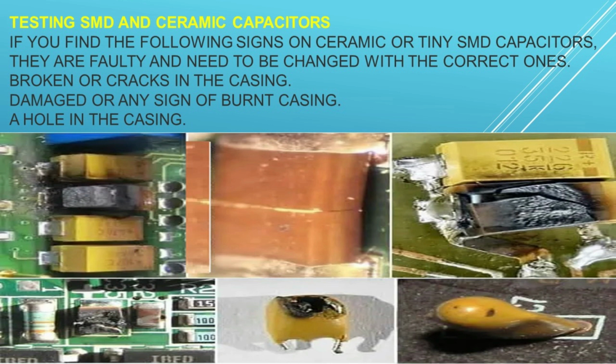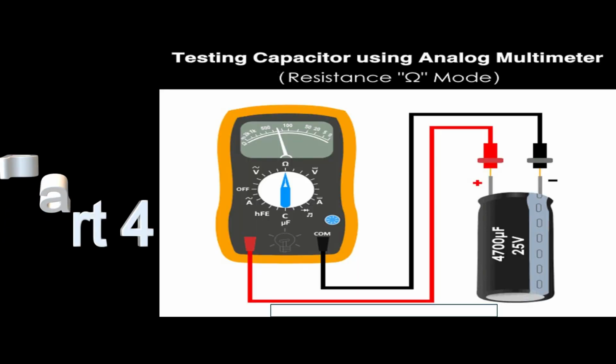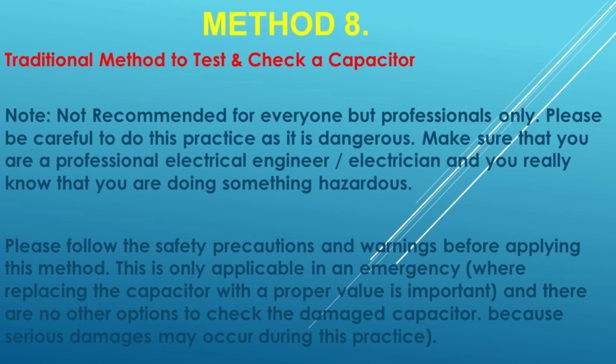Bulging top vent of capacitor. The top vents of the electrolytic capacitor in the shape of K, T, or X are the weak points made to release the pressure during the failure of a capacitor, to avoid serious damage to the surroundings and any other components connected near it. If you find a bulging top of the capacitor, it is the electrolytic discharge, black, white, or orange color, which depends on the electrolytic material, i.e. the capacitor releases gas pressure during failure and breaks the top vent of the capacitor.